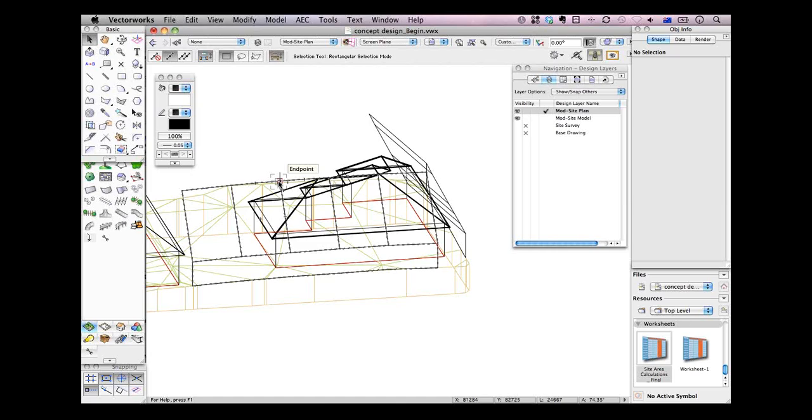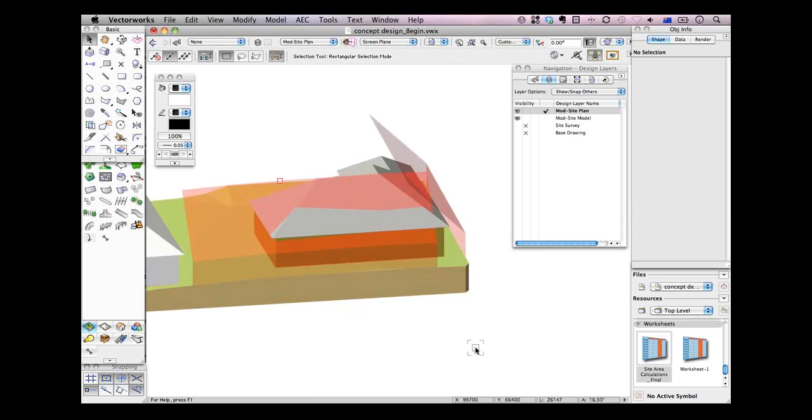So when I render, I should see whether my building is complying. Now there's a big grey area on my roof, and the rest of it's this pinky colour. The grey area is actually penetrating my height boundary or my recession planes or my setbacks. So I have to go back to my model and push it.